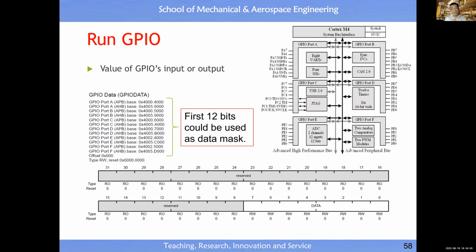Assume in this case, let's say pin number 1 from port A, I must produce a positive pulse, then make a transition to 0, 1. So basically you just write the 1 here, send out, and immediately there's a 1 at the pin. Bit 1, you write the 1 here, then the corresponding hardware pin will be logic 1.